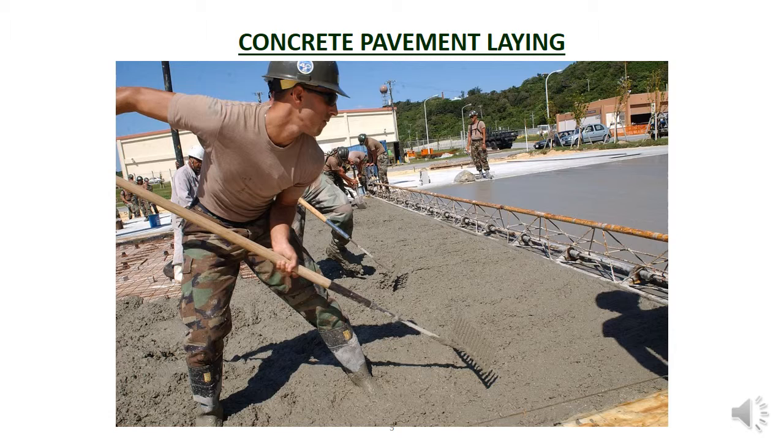Note that the screed is a truss beam, which is what is required to span the whole width of the road without sagging. A sag in the screed would cause a depression in the bottom of the road, which would pond water. The concrete needs to be vibrated in place to remove air entrapped in the concrete, which would otherwise cause voids, and to create a dense, strong concrete structure. This may be done with handheld vibrators, or the screed may have a vibration unit connected to it to vibrate the screed, which may be what the unit on top of the screed is in the background.